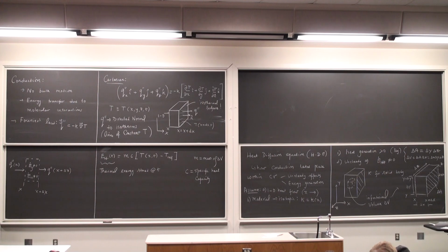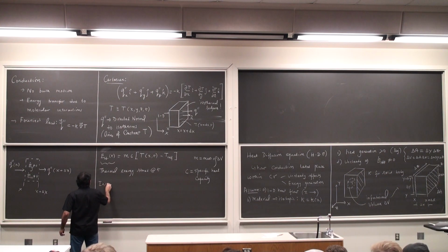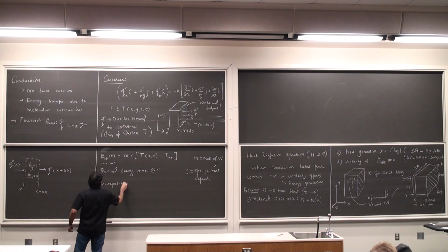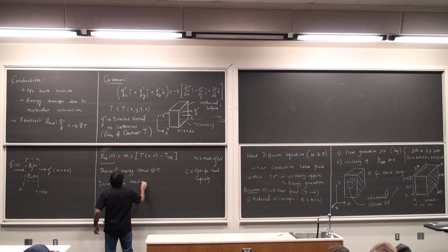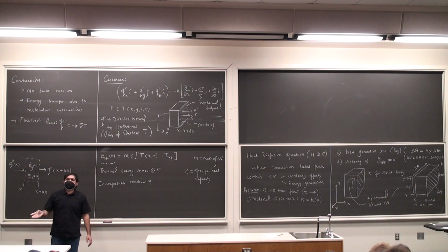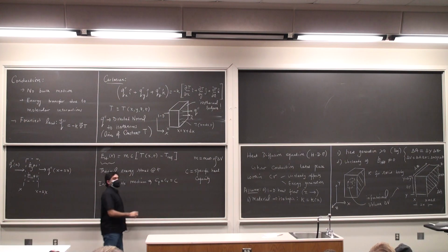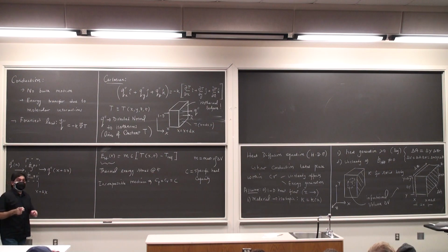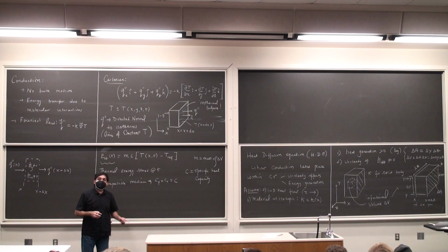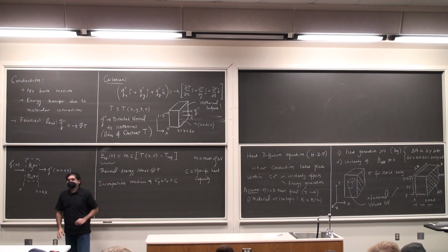Specific heat capacity, of course there will be this confusion in your mind: is this guy talking about specific heat at constant pressure or at constant volume? That's a very valid question to ask. We're going to assume an incompressible medium, which means that the specific heat at constant pressure and constant volume are the same, so Cp is the same as Cv. We just call it C. What do you do in case of a compressible medium? We don't deal with that in this course, but if you do, it is experimentally validated that Cp is a better choice than Cv. Okay? But we're not going to deal with that.